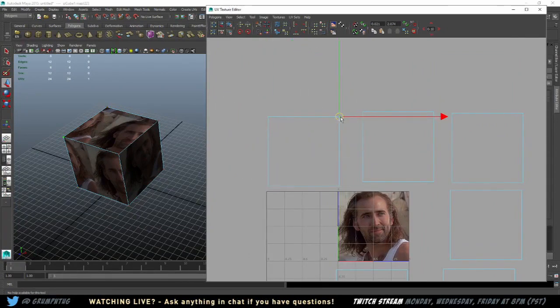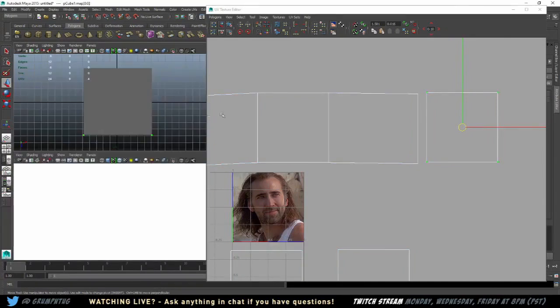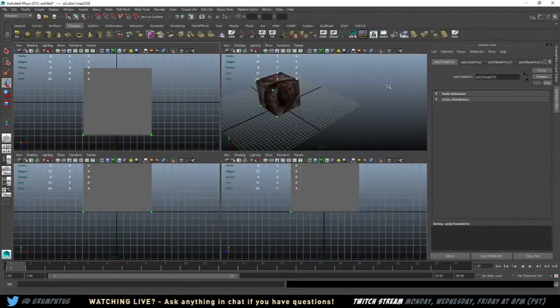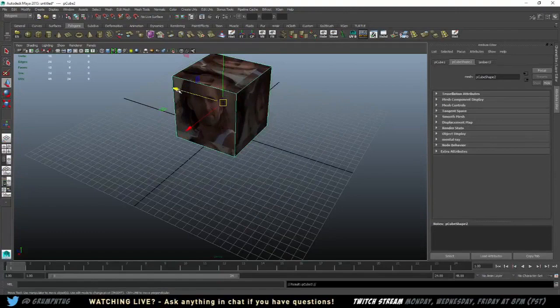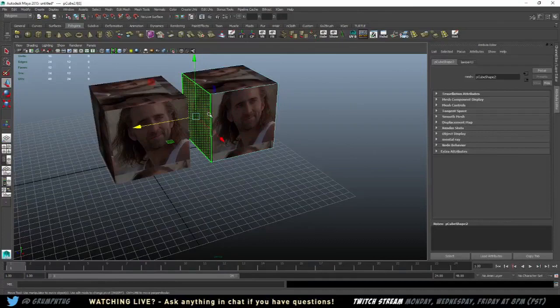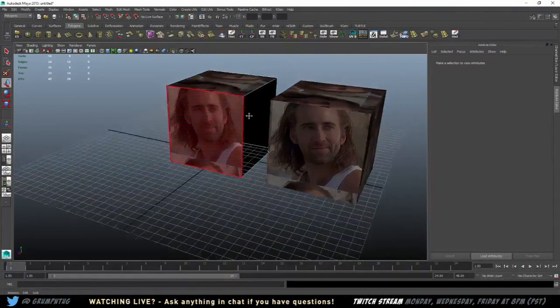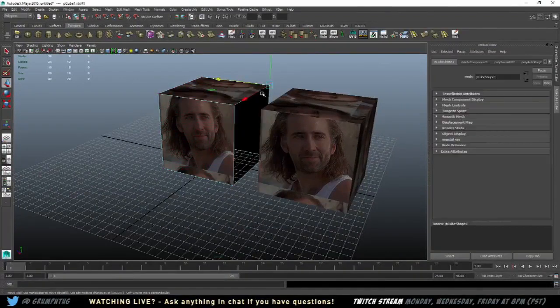The other thing you can do is weld vertices to each other. So if you hold V, just like in 3D, you can drag them to each other. So they'll weld to each other. And the reason you'll want to do this is, let's say I've got, let me get back out of this. Let's say I have two models. There we go. Face. I'm going to get rid of these faces because I want to weld them together. Face. There we go.